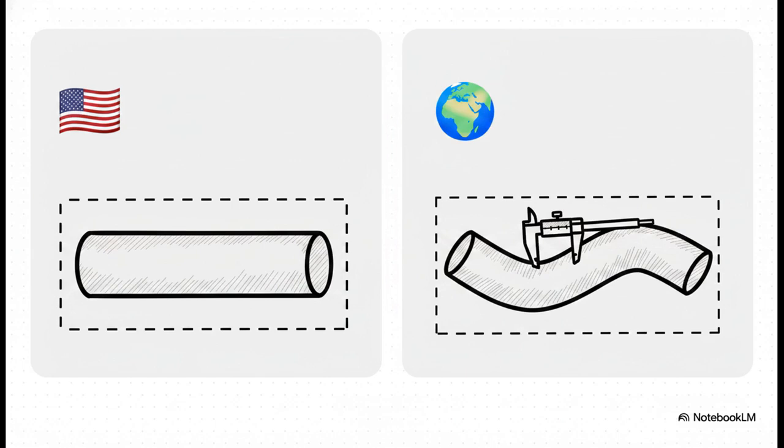But if you're working with the ISO standard, which is common in Europe and globally, the size tolerance only controls the 2-point local size. It does not automatically apply this envelope boundary. This means under ISO, you could technically receive a perfectly measured, yet totally bent and completely unusable pin unless you explicitly ask for the envelope requirement by using a special symbol right on the drawing.